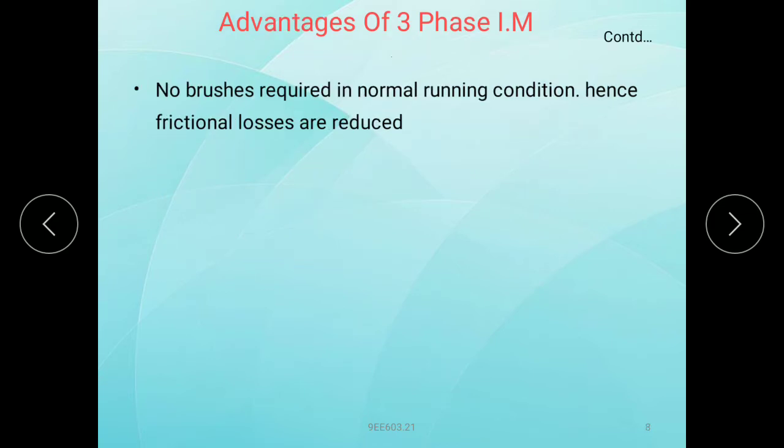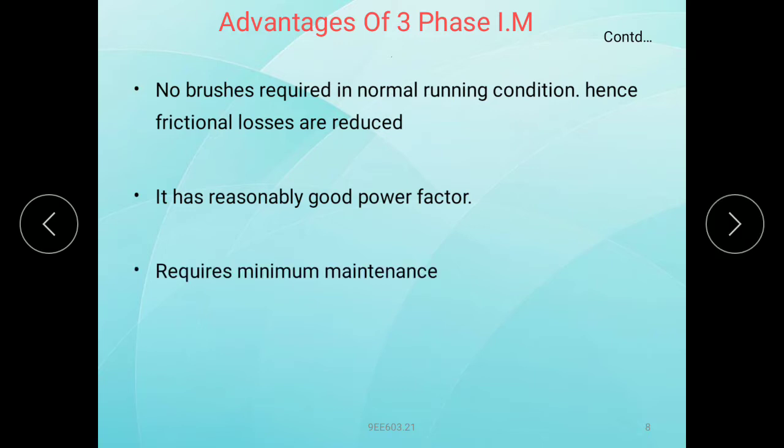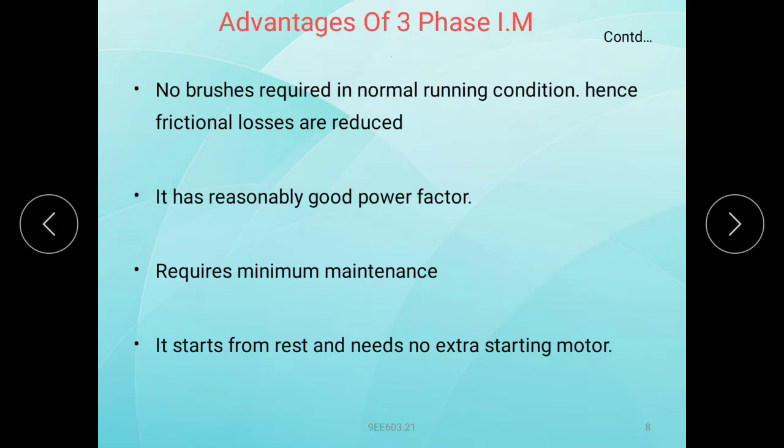No brushes are required in normal running condition, hence friction losses are reduced. It has a reasonably good power factor, near 0.8 lagging. It requires minimum maintenance. It starts from rest and needs no extra starting motor.